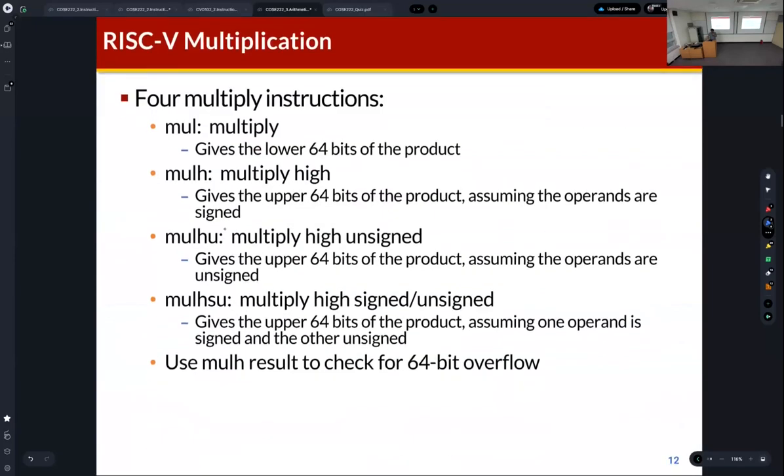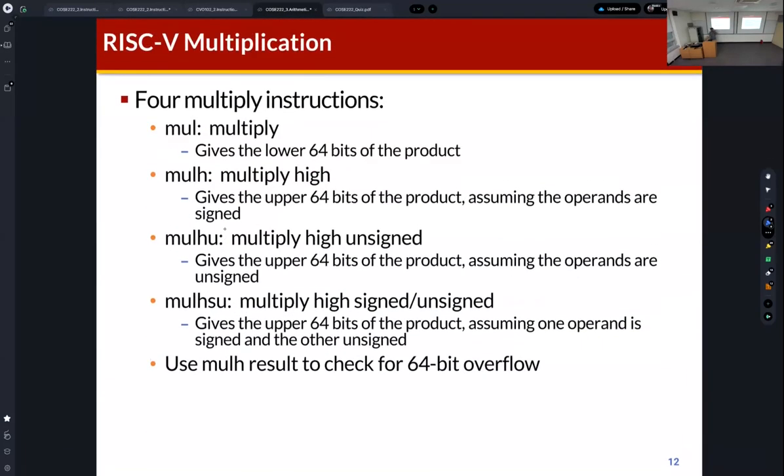Then RISC-V supports the multiplication instruction, but in order to use it, we need the M extension. In lab number 2, we added the M extension in the compiler, right? So the generated assembly includes the mul instruction. Mul is the multiply.